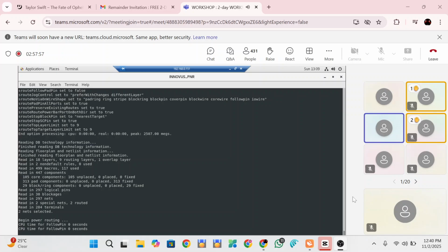But what is it actually? Let's say you have a group of standard cells you have to place, but what is the tool doing? It is splitting the logic, one side of the logic to one side and the other half of the logic to the other side. You will create bounds and guides in your design to place them in a particular location with a guided placement. That is called a structured data path, because the connection to the flop should not miss, it should not be scattered, it should not be clustered, it should not be split.